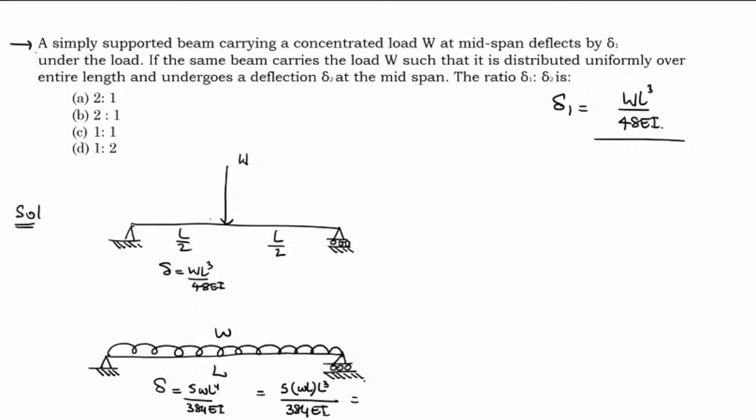So this I can write as 5 WL cube by 384 EI.